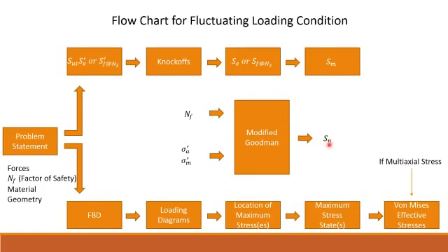Now notice I don't know N. I know what the strength desired is. If I have this strength, then it'll have this factor of safety. And then I can take this strength and start my top half, all the way down to Sm, and now I'm going to solve, rather than for Sn as I've done in the past, for the number of cycles in this equation, S equals A times N raised to the B, as we talked about before.